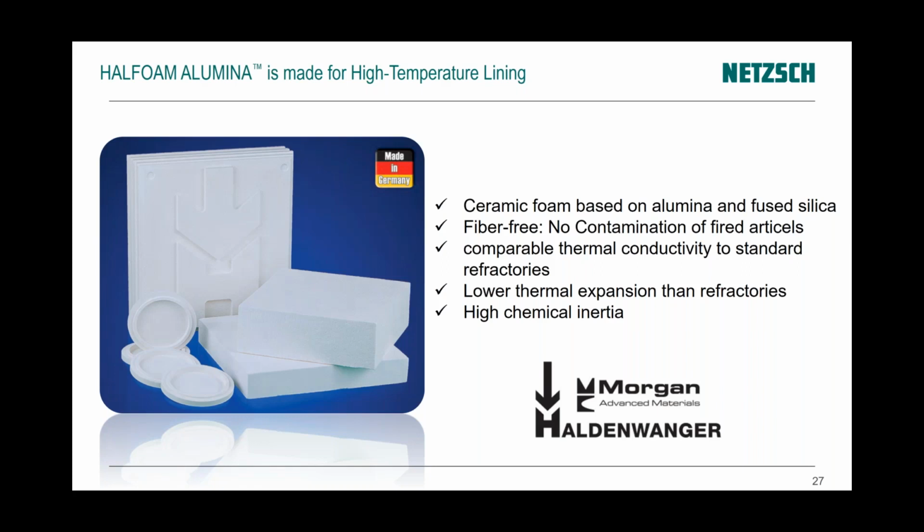This material is fiber free, so you will have no contamination on fired articles in your furnace. It has a comparable thermal conductivity to standard refractories, a lower thermal expansion, and a high chemical inertia. It is based on alumina and fused silica.